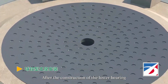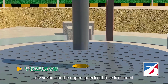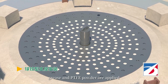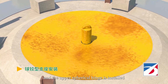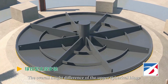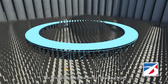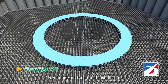After the construction of the lower bearing platform is completed, the surface of the upper spherical hinge is cleaned. The PTFE sliding plate and the intermediate pin shaft are installed. Grease and PTFE powder are applied, and the upper spherical hinge is installed, completing the installation of the spherical hinge. The overall height difference of the upper spherical hinge should not exceed 0.001 rad. The installation of the swivel bearing type is generally an integrated installation.